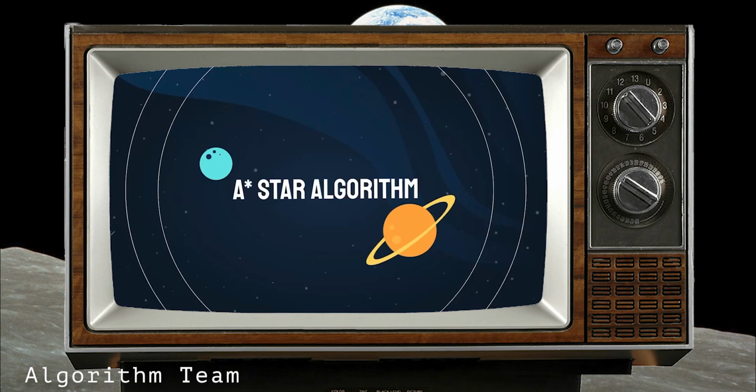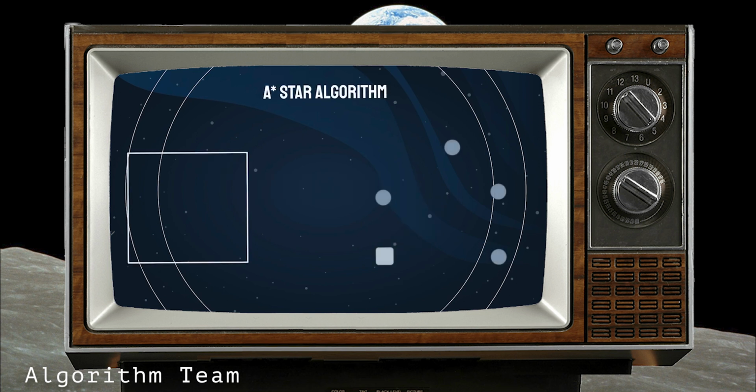To provide a path for the robot to follow, the algorithm team chose the A-star algorithm to search for the shortest path, using Euclidean distance for the heuristic. Factoring in physical limitations, we conceptualize a search graph with a maximum vertex degree of 6 for the possible actions that the robot can take. The action costs are reflected as weighted edges to indicate preferred actions.